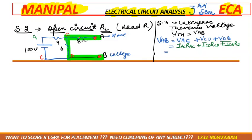Is there any current flowing across AC branch? Yes or no? It's an open circuit. So, in an open circuit, current will flow? Yes or no? No. So, it would be ultimately 0. Correct? Now, ICD we don't know. RCD is how much? That is 6 ohm. Correct? Similarly, IDB is also 0 only. Correct? IDB is also 0 because it's also an open circuit.